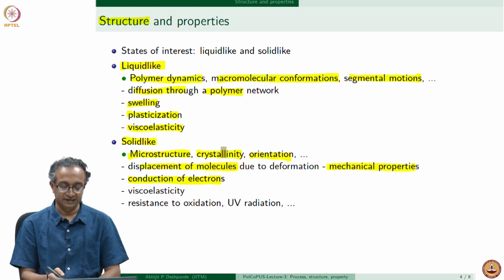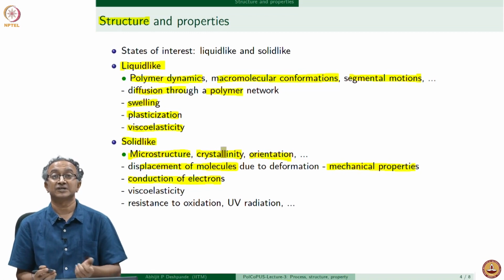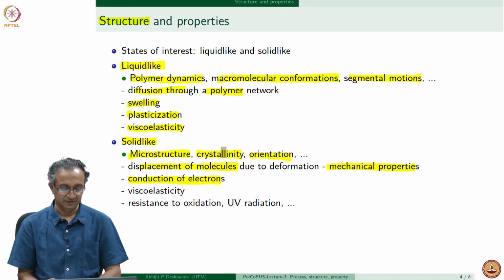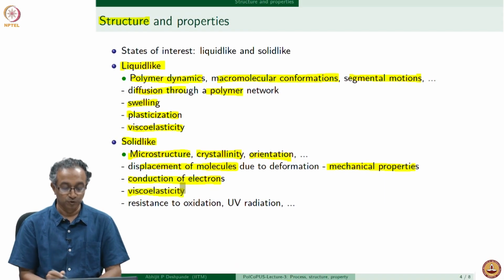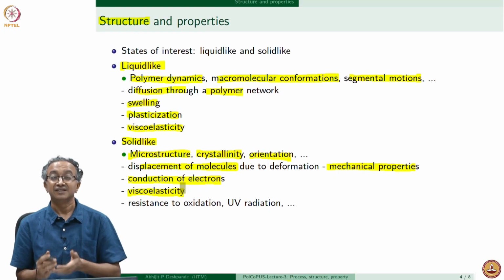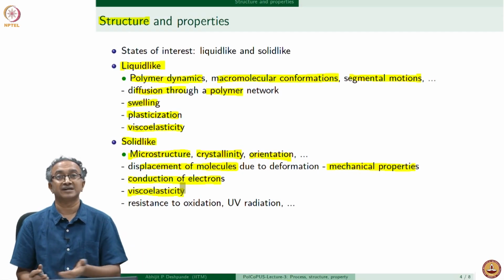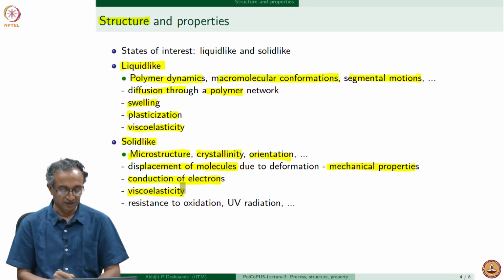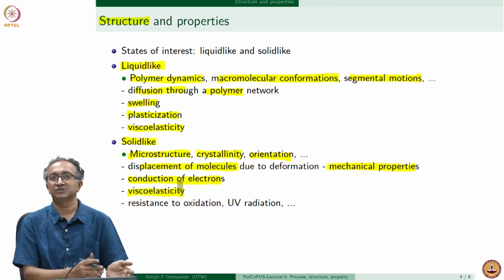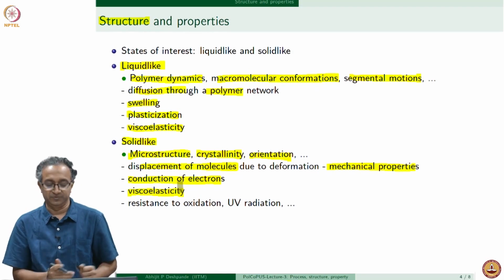So whether crystallinity will enhance conductivity or whether amorphous material will enhance conductivity, we will see. Structure is again closely linked with property of these materials. And in the solid state, though molecules seem to be frozen and therefore we get a solid-like character, there is some liquid-like motion possible over long term or at high temperatures. Therefore solid-like materials will be viscoelastic, which means they will be predominantly solid-like with a lot of elasticity features but with some viscous features also.